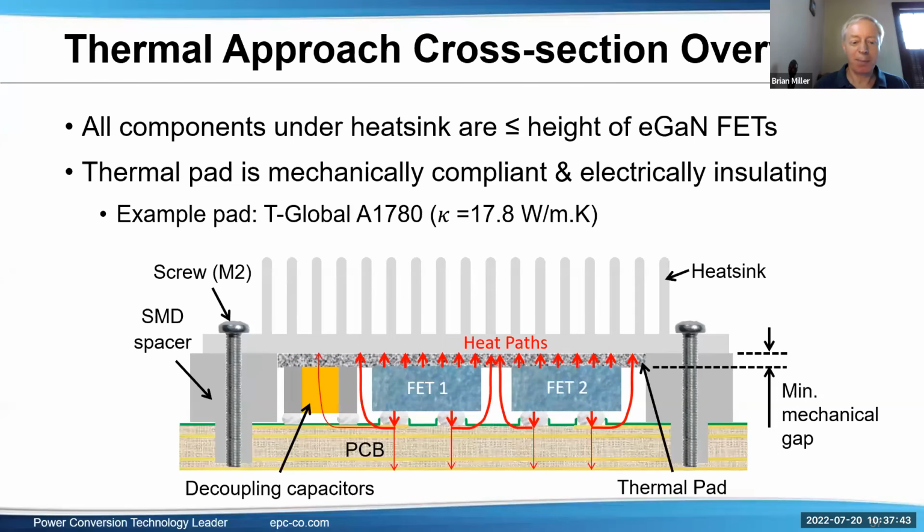If that does become a problem, another way which isn't shown here, instead of a capacitor, there are aluminum heat conduction devices that can be bought, or even just cheap resistors that can take high current can be put here. So that's an alternate path to taking heat from the board up into the heat sink, and maybe, like you implied, having the capacitor not right in that area.